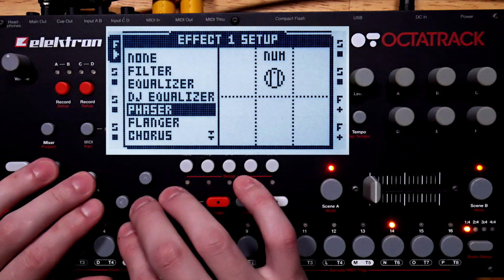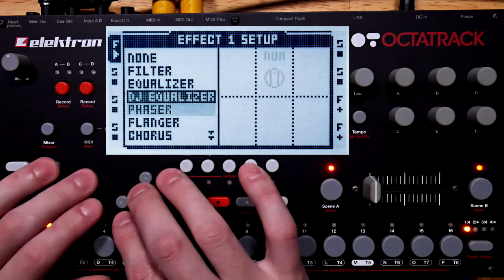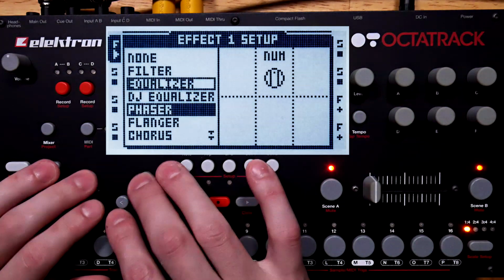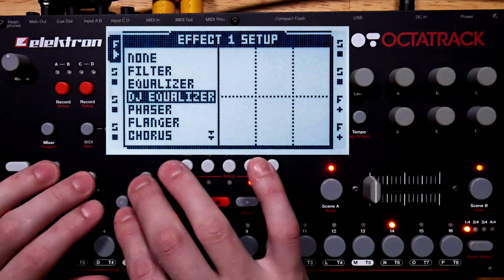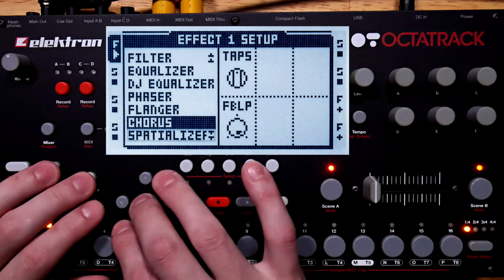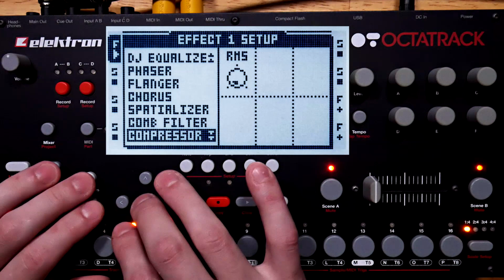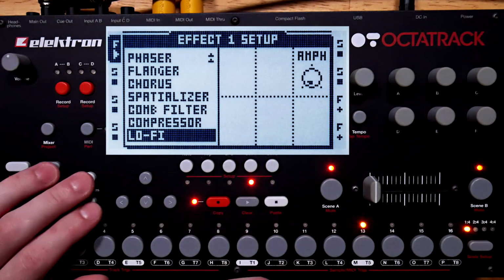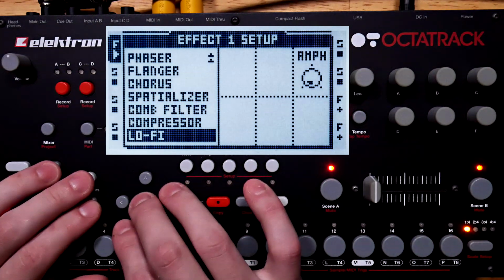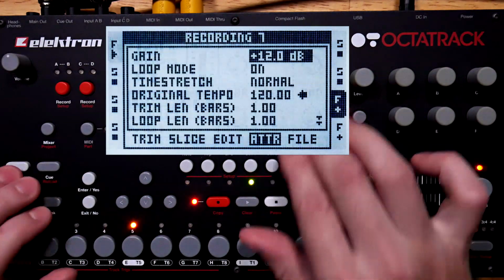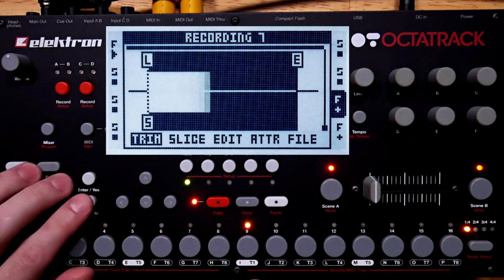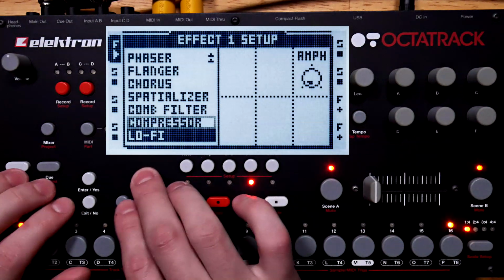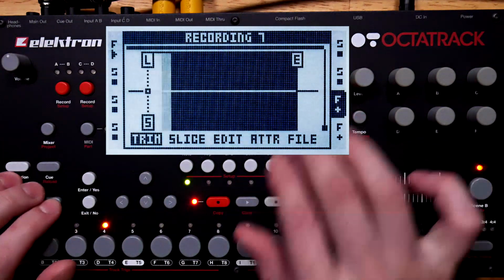The primary offenders are the filter, DJ EQ, and lo-fi effect. Switching to the compressor also causes a click, but that's primarily because the compressor by default is 100% wet. The lo-fi effect is the most egregious, immediately leading to lost signal level. It's rather clear from looking at the waveforms that the lo-fi effect is internally clipping with a rather low threshold. We can clearly see a difference in the pre-fader level recording.